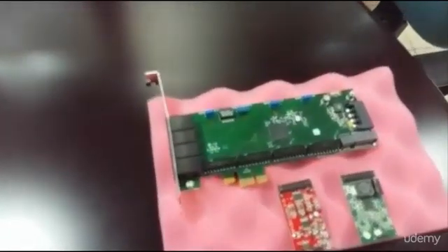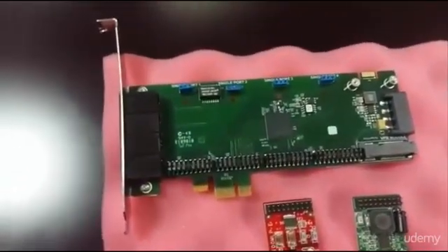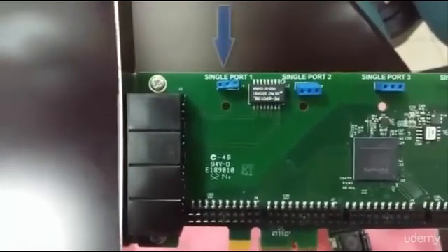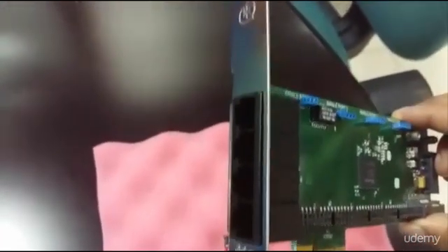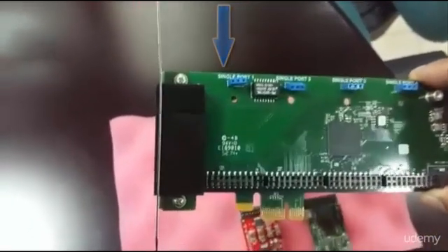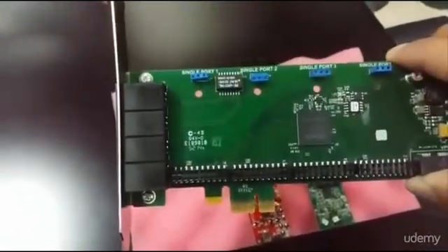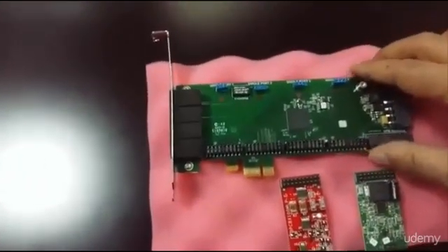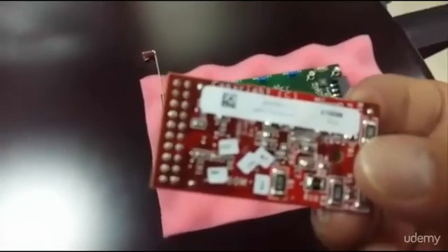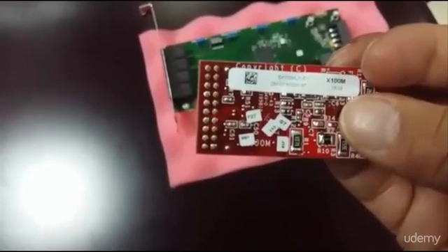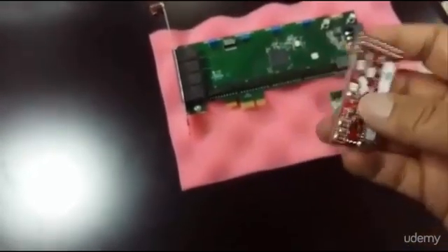Here I would like to show you the DGM A4 series analog card. As you can see, the base card which is having 4 ports and the port numbering which matches starting from the top. As you can see here, this is the base card, and what I need to do is to install or plug the FXO and FXS module. So maximum I can use 4 FXO. That means I can connect 4 phone lines, 4 incoming CO lines from the local phone company.